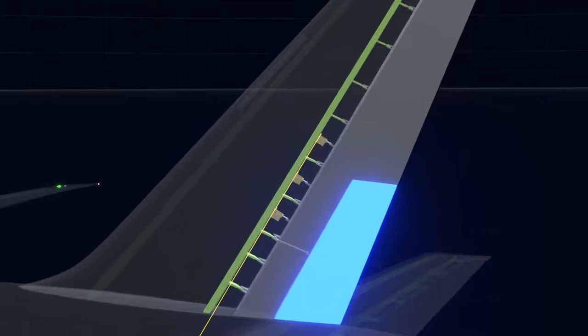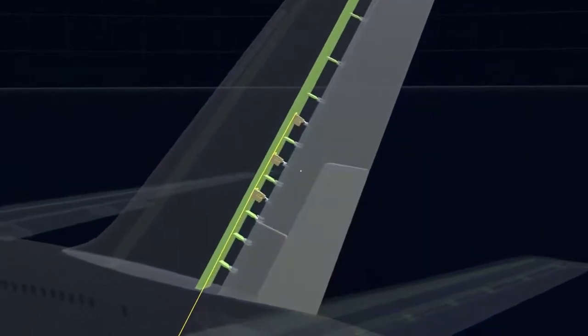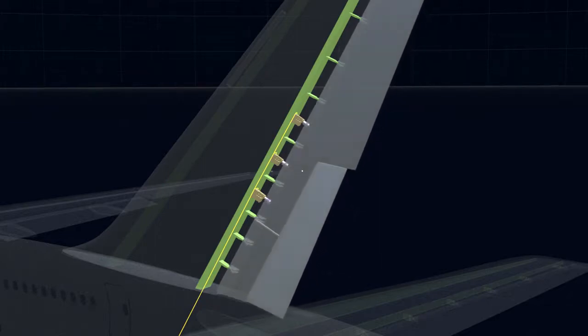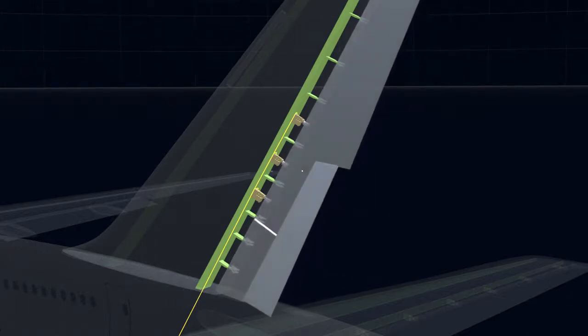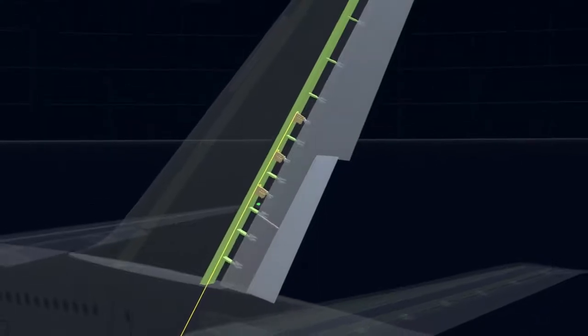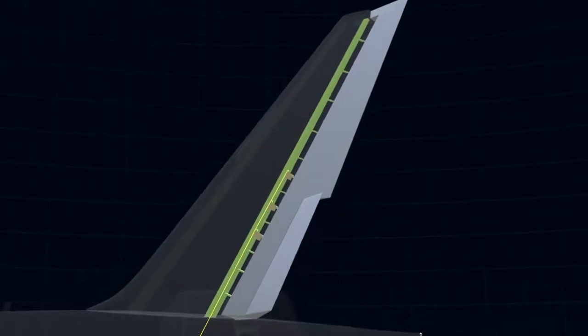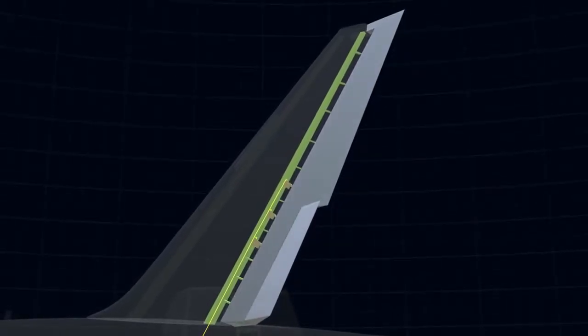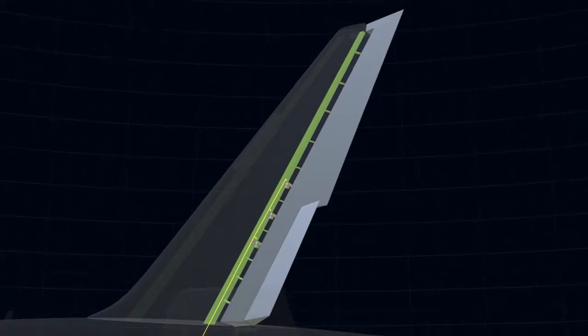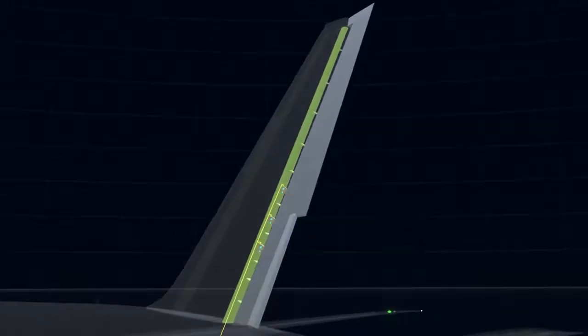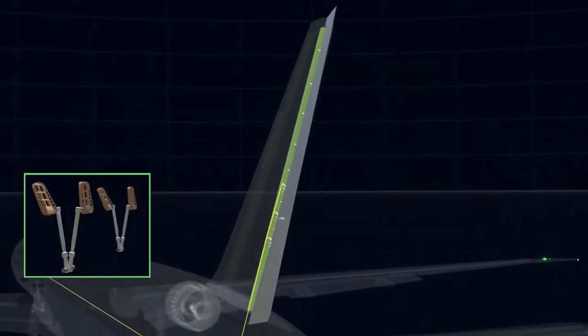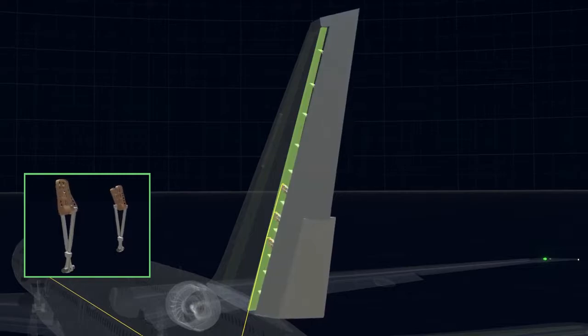The 777 has a rudder tab connected to the rudder. When the PCU actuators move the rudder, the tab moves along with it. But the tab also has mechanical rod connections, which deflect it further ahead of the rudder displacement. The mechanical connection is rigged to move the tab twice the distance of the rudder movement. By slipping further into the airstream, the tab increases the overall effectiveness of the rudder. Position transducers on the PCU send the rudder position to the primary flight computers. This allows the computers to control the rudder with precision.